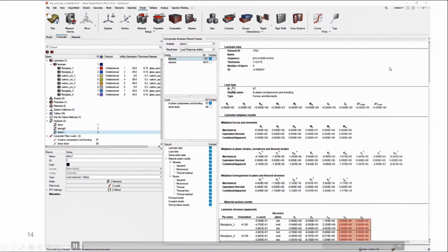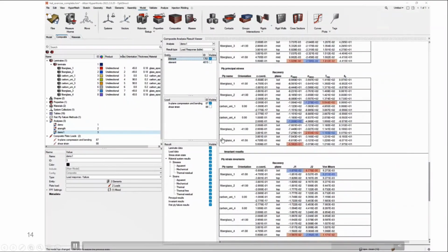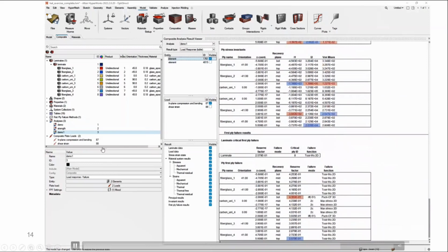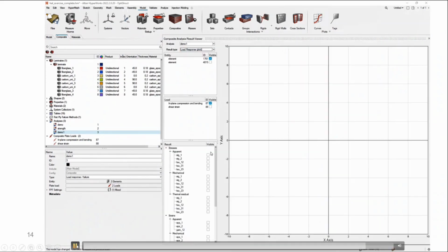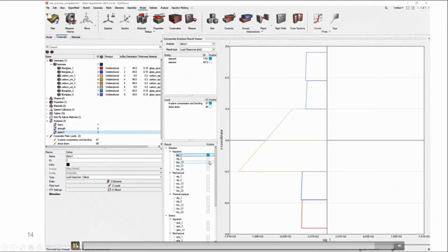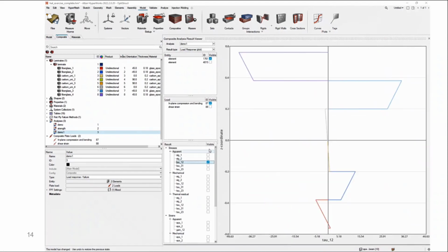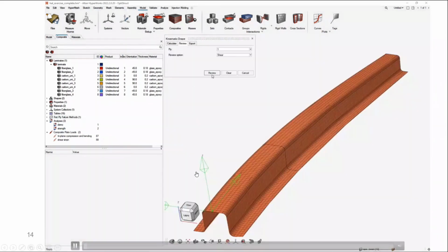So, well, a 6-degree change in some of the areas. And with the given load that I've defined here, so that's a predefined composite plate load, we can actually see that the reserve factor is basically less than half of what we had before. So there can be significant influence of the draping data towards your results. Yeah, and that was just the first quick feature.